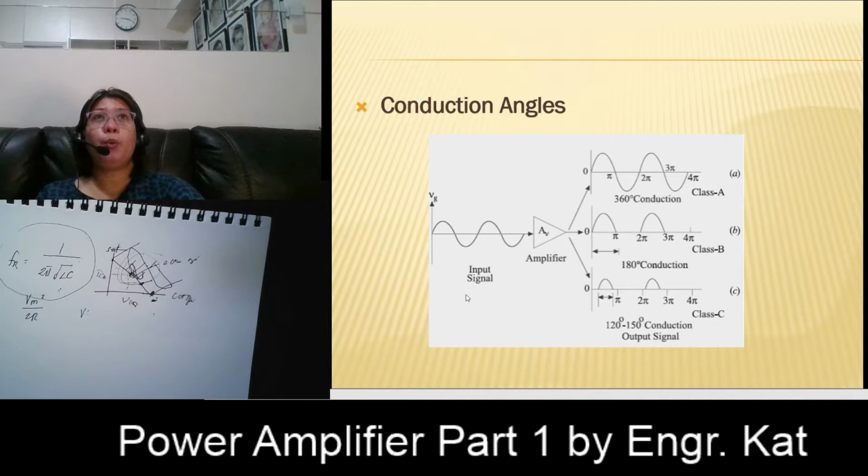Okay, so in classes of power amplifiers, we're not usually concerned with the amplification. Our concern here is more on the power that is converted from DC. So it is more on the efficiency and not on the amplification of power, because power amplification is your input AC power versus your output AC power.